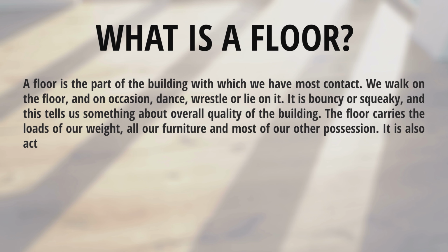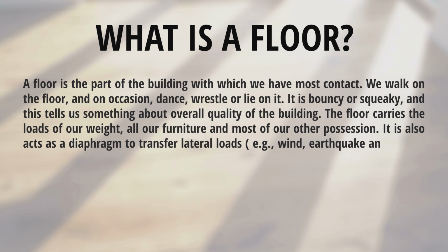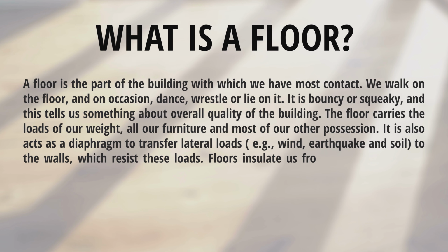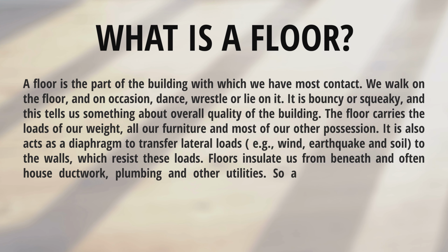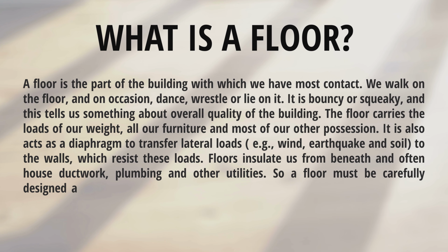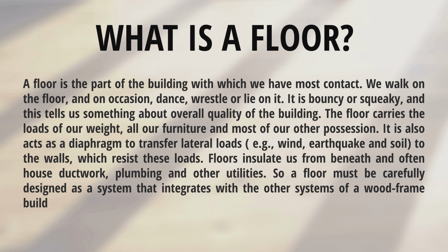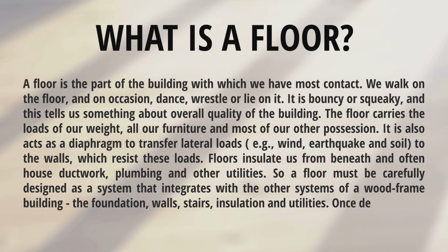It also acts as a diaphragm to transfer lateral loads, e.g. wind, earthquake, and soil, to the walls, which resist these loads. Floors insulate us from beneath and often house ductwork, plumbing, and other utilities. So a floor must be carefully designed as a system that integrates with the other systems of a wood frame building: the foundation, walls, stairs, insulation, and utilities.